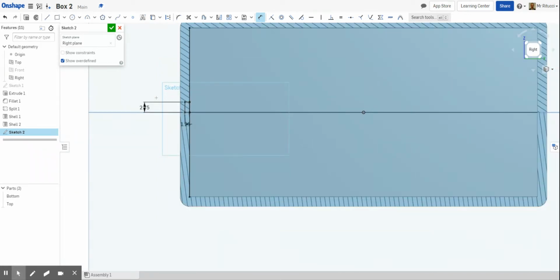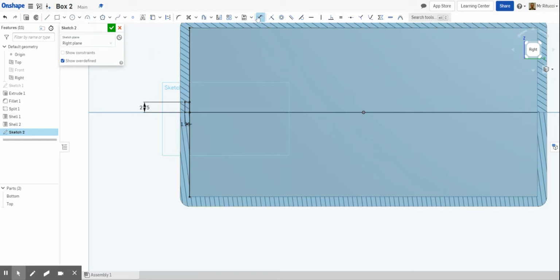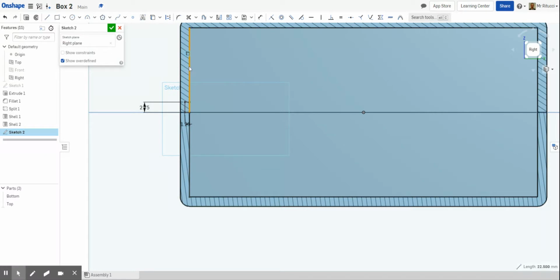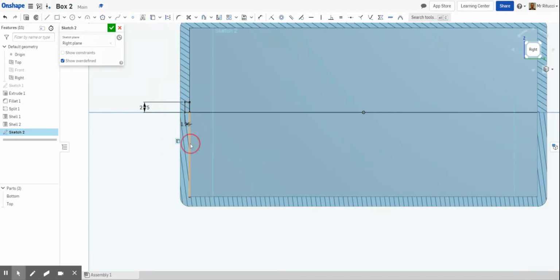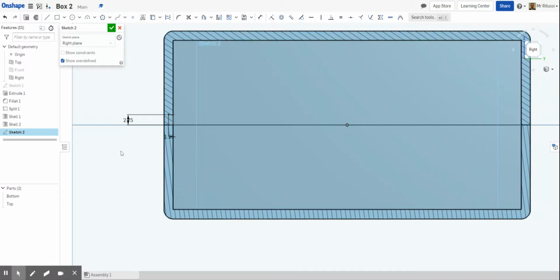Great. Now that's done, I'm going to turn off the dimension tool, and I'm just going to click it, and delete that geometry I projected before. Don't need it anymore. The important bit is this bit here, and I used the geometry inside that line there to project onto the work plane so I could draw that part there. It gives me just a reference point, which makes things more accurate.